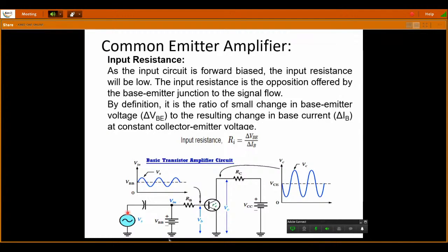I apply an alternating current signal with different frequencies, from zero frequency to the largest frequency, with a finite magnitude at the input, and then verify which frequencies are allowed by that CE amplifier: for which frequencies it has less gain, constant gain, or more gain. We can do all those things using AC analysis.